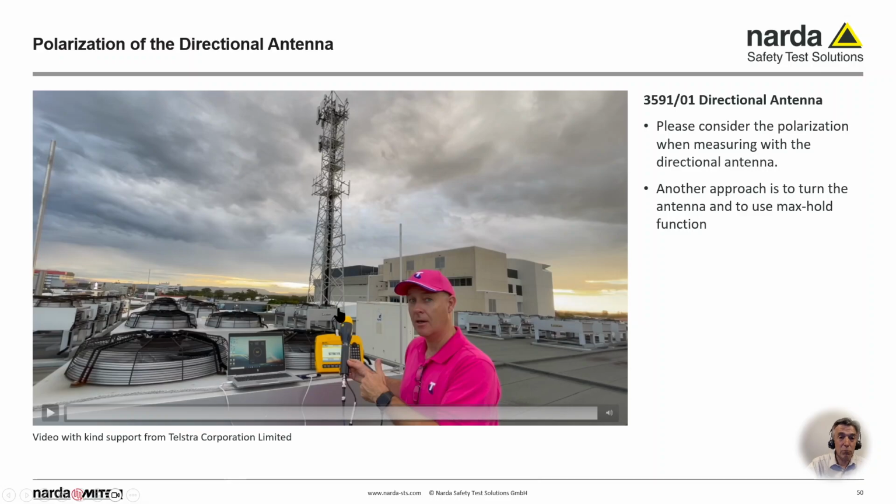And normally I also don't do those two measurements and add them together. I'm a little bit lazy. I put the instrument into max hold and turn the antenna a little bit. Okay.